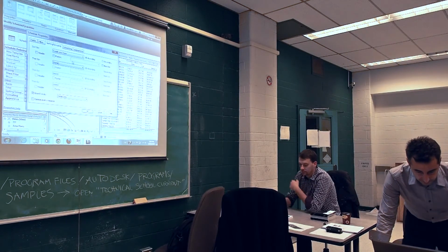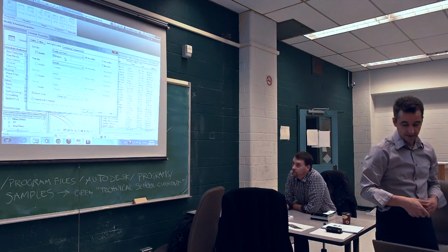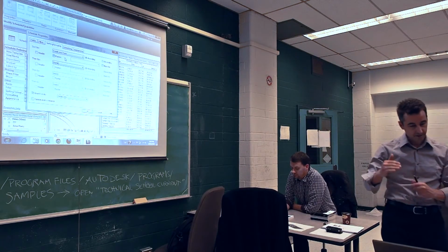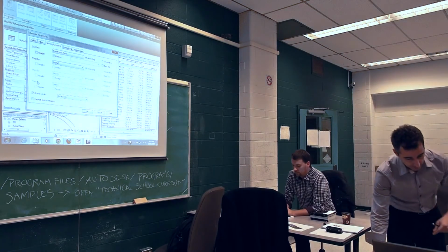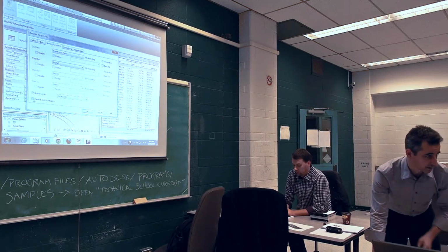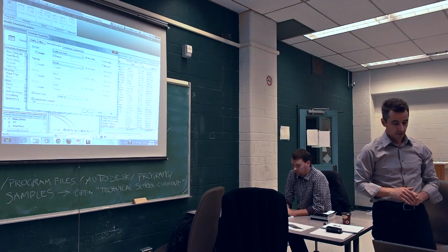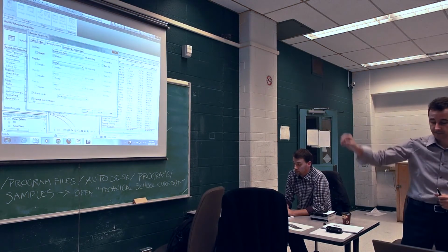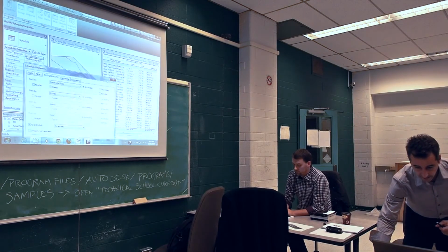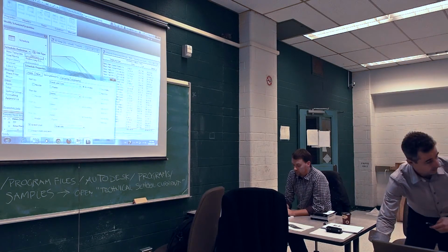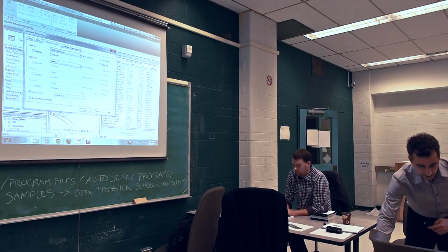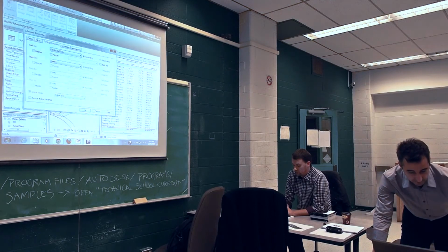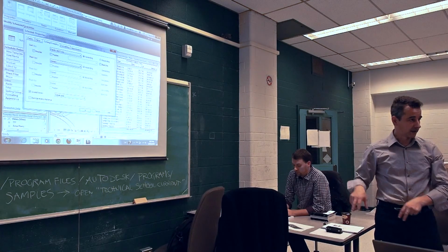So let's go to sorting and grouping, and I notice that I have sorted by family and type, right? So I want all similar family and types in name to be sorted and grouped together. And I also notice I have itemized every instance if I have to list every single one of them, or I can uncheck that. If I uncheck, only once will be listed in the schedule, and that's how I had it presented here. Right? I have only one basic wall, PW 1.1 concrete block. I also have enabled grand totals. That will take care of these values. It's going to show grand totals at the end.